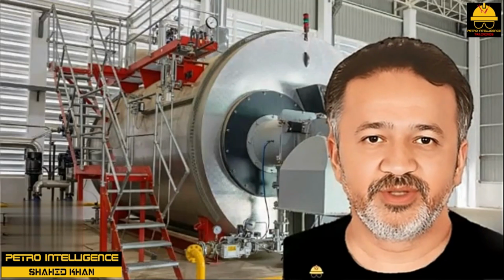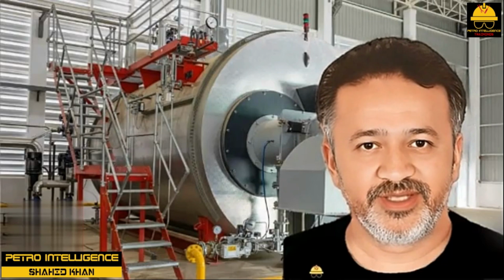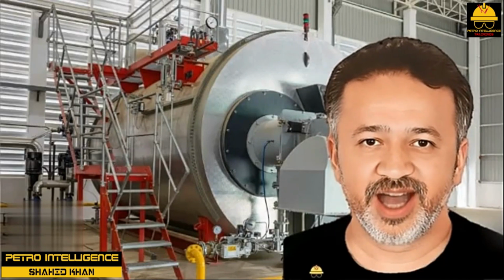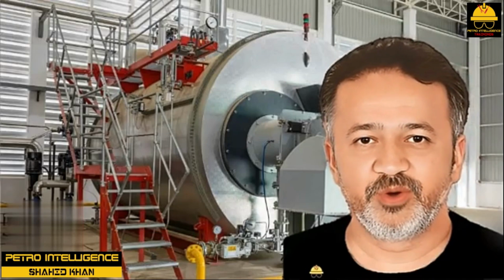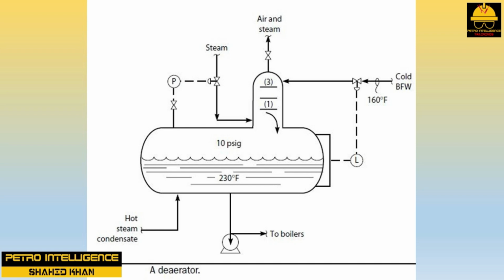Deaerators. The humble deaerator, operated by the utility department, is an interesting and important component of any process facility. Oxygen is a highly corrosive element and if left in the boiler feedwater would rapidly oxidize the boiler's tubes. The dissolved air left in boiler feedwater, BFW, is stripped out with steam in the deaerator shown in this picture. The cold BFW has been taken first from the river and then filtered to remove sand and sediment.